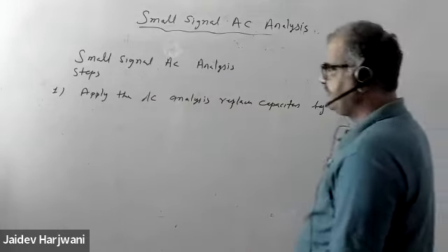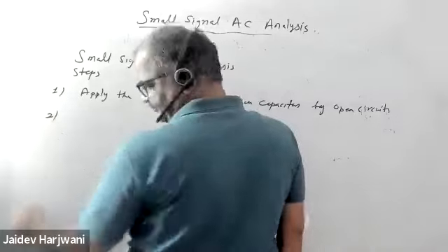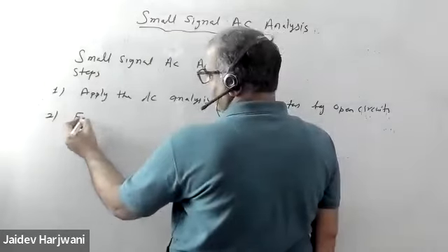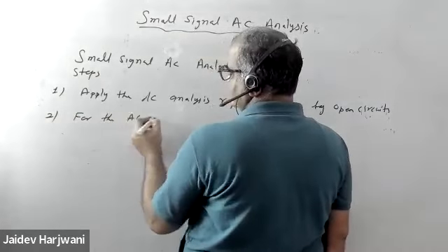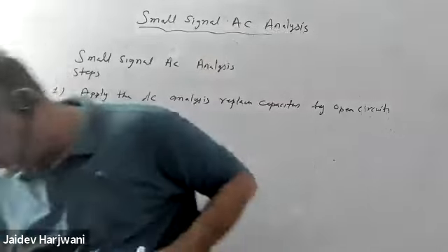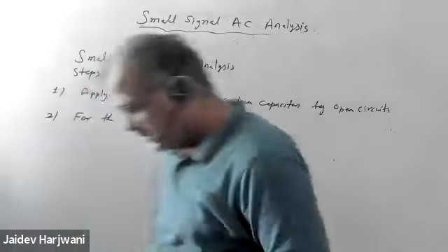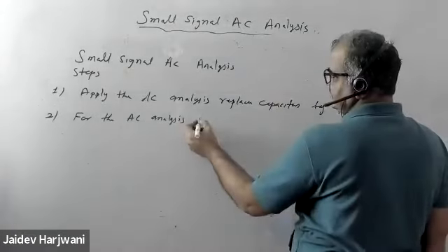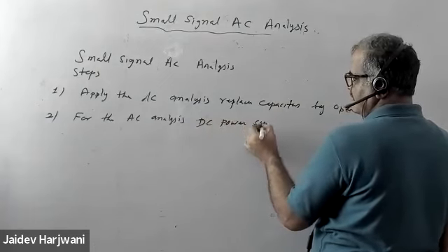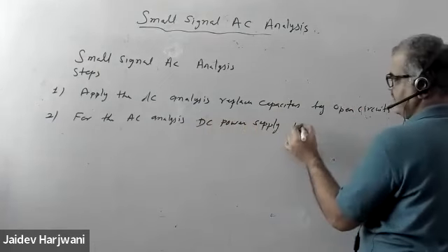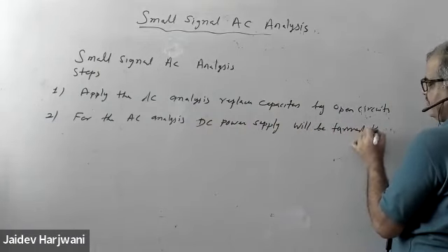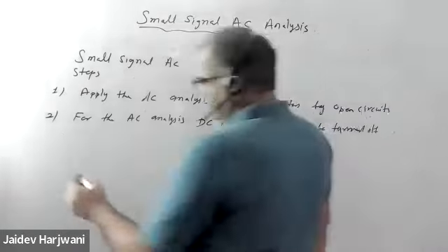Number two, for the AC analysis, short the power supplies. That is, for the AC analysis, the DC power supply will be turned off.